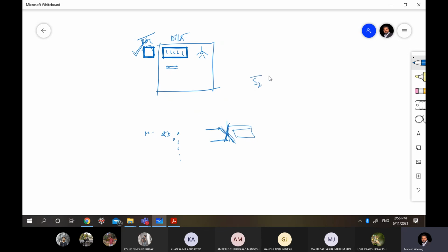Okay. But in the case of S2 bar, S1 bar and S0 bar, before starting the operation I want them to be inactive. Meaning they should not do any work initially, memory and so on. Only when I say so, you have to take the signals. Okay. And they will be inactive when they are 1. Are you getting it? So initially all will be 1 and after that they will take proper 1 and 0. Are you getting it? It's not that initially they will be either 1 or 0.